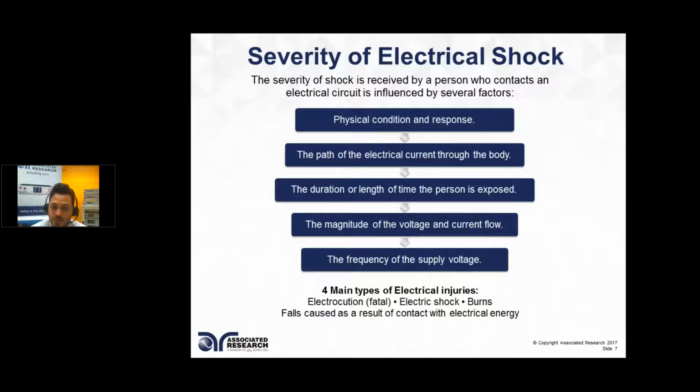Then there's burns, where there's that inability to let go, and that current is flowing through that wire, which happens to be you, right? For a long time. And just like that's why we ground bond test, right? Let's inject a large amount of current into this wire and see if it holds, or will it burn up? Well, our bodies and our nervous system do the same thing. Our blood vessels do the same thing, right? Perhaps they can carry that current for a while, but the longer that is, the more likelihood that we will get burned.